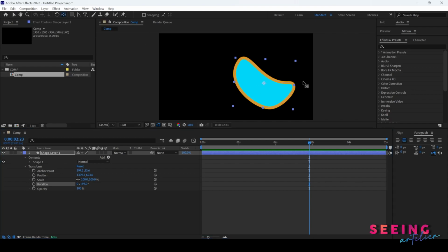You just click on it and match the center that you would like to have. If you open the snapping, it will arrange it in the center of the whole shape layer. When it snaps, you will see that there's this square shape around the anchor point. So this is snapping. If you didn't turn it on, you can always hold down your Control and move it around. You'll be able to snap your anchor point to the center of the whole shapes as well.